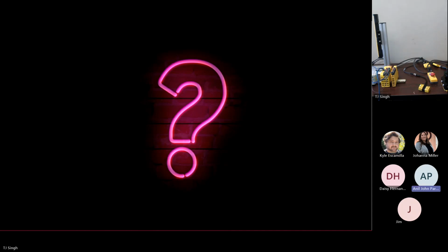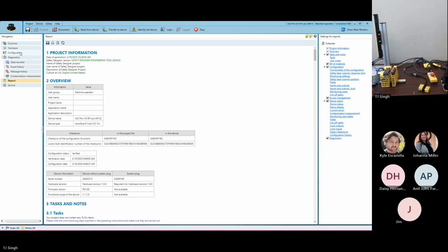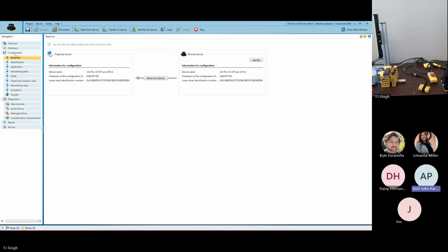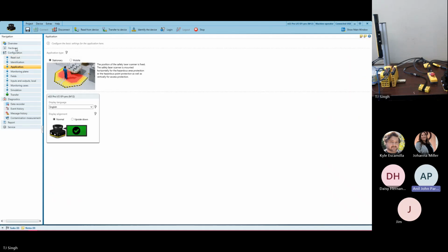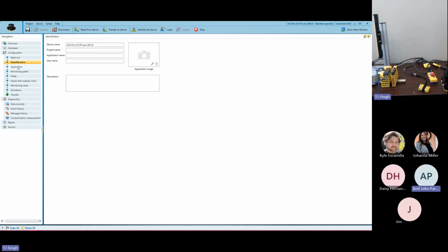It was just more like if somebody changes something in the device later on, and then you have an incident. In safety programming, you generally have a checksum. Oh, there is a checksum for configuration. I saw it a moment ago. So I just wanted to make sure. And then can you lock it down? That's the other thing. I know this is a hardwired output, but is there a PROFIsafe version of this?